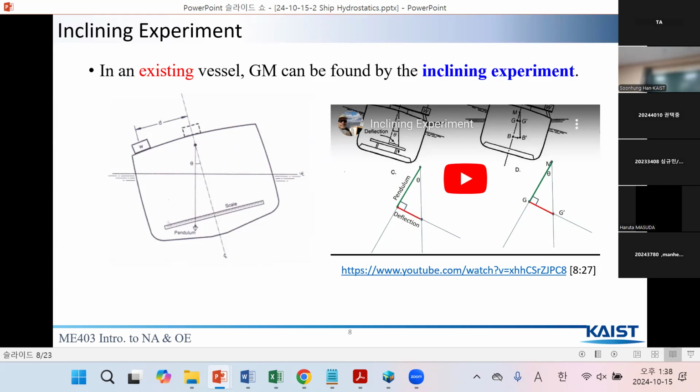That's why, as a ship owner, the cargo carrying capacity is important. It is contracted with a signature. That's why we should check the exact weight of the ship and also the position of the weight, KG, for the stability. Also, if the ship is unstable, G is too high, then you cannot carry too much cargo.